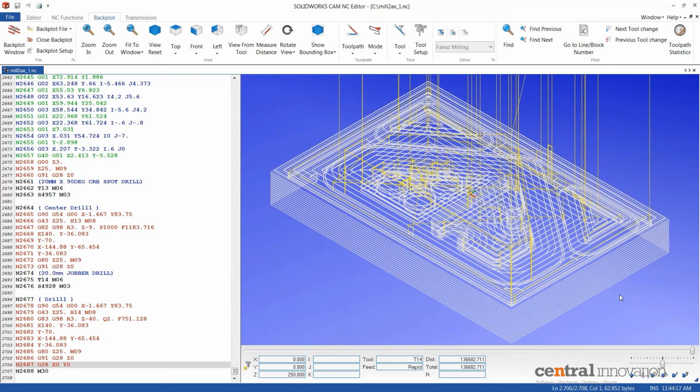But basically, I've always found it fairly useful to go through this process to identify if there are any issues prior to exporting this out to a manufacturing machine. As most people would have probably been tripped up with some NC codes somewhere along the line, and this really just gives you a safety net between taking it out of SOLIDWORKS and putting it out to the machine, to make sure that the code is actually going where you expect it to go.